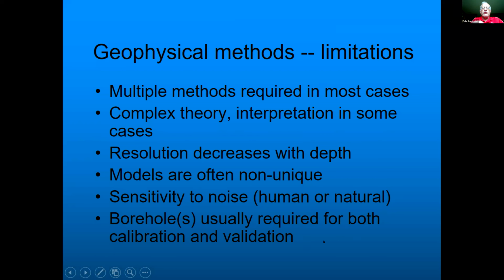And then boreholes are usually required, both calibration and validation. Actually, I don't have any borehole data for you in this presentation. I was going to add that, but I never had time to add that in. But subsurface information is very, very important to validate your geophysical interpretations.